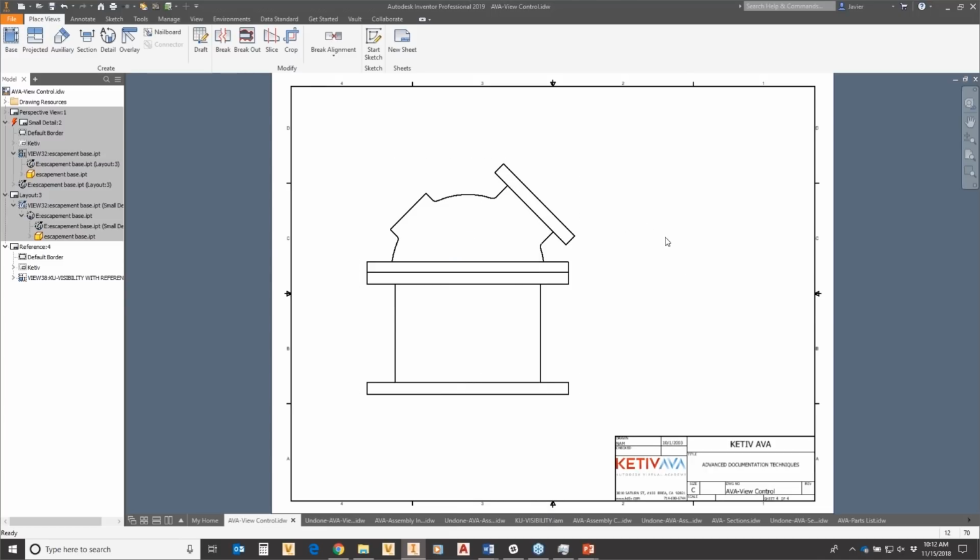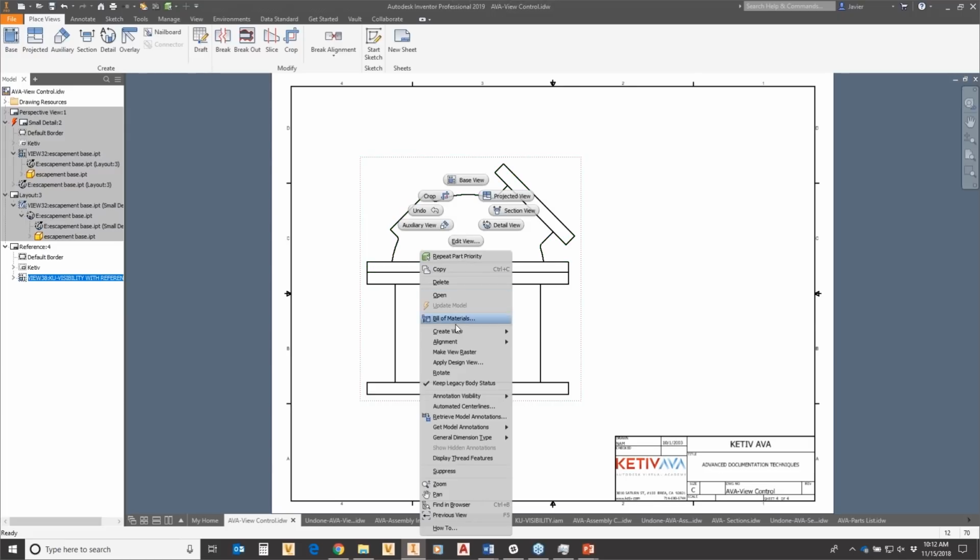So make sure that when you're working with your drawings, you shift right click so that you pick what it is you want. In this case, I want to pick parts. Now I've picked the part, and because I've picked a part, I've got part options, right? So a number of things we could do. We can certainly suppress it. We can show it in a number of ways. But again, we're able to show this almost any way we want.